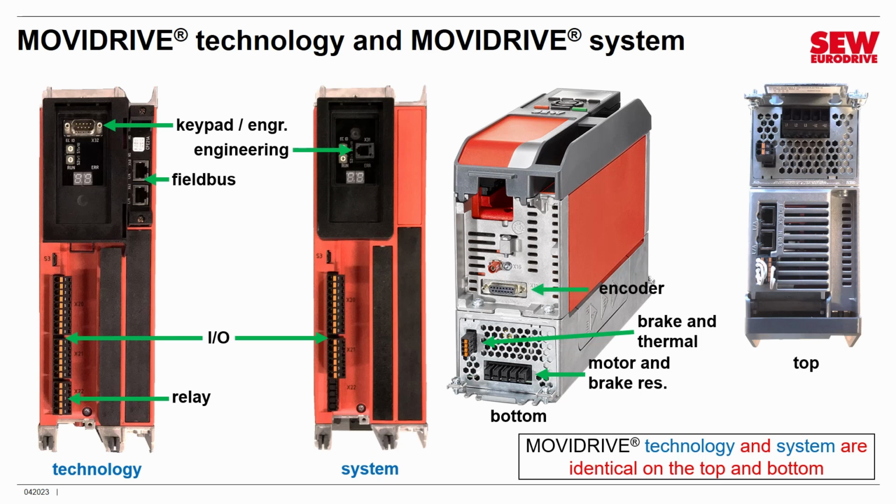There's the connection for the multi-type encoder. Plug it in there, and the DDI connector, if you're using a DDI motor, that digital motor interface, there's the connection for the little teeny coaxial cable right next to it. On top is line in. This is where you would connect up the 3 phases to the power supply and also, of course, the ground connection. This is where you put in 24 volts to provide the energy for the electronics.